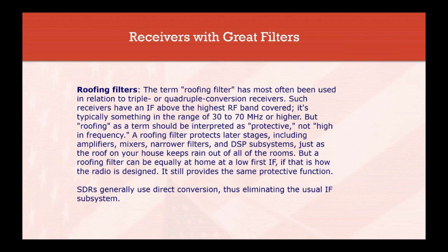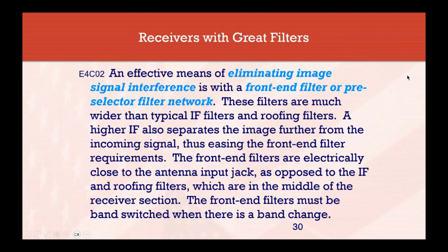Let's see. Software-defined radios generally use direct conversion. This is what we were talking about earlier with those fast A to D flash converters, where they don't have to have the IFs there to do that at all. That's some of the new technology and the new techniques that's come our way.